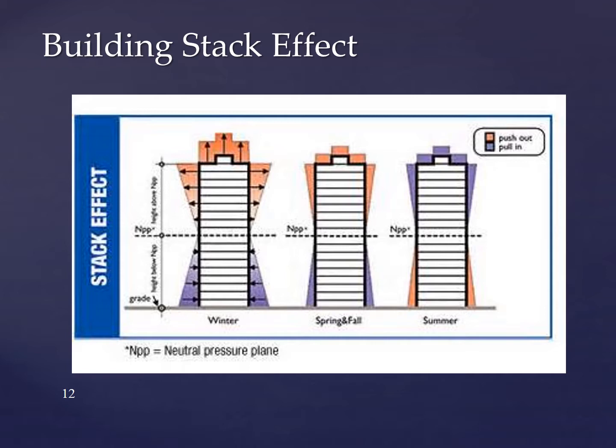Something else that we don't often think about is stack effect. This is a great diagram that shows how air movement changes seasonally. This is one of those things: our buildings breathe. They're living, breathing. Our envelope breathes. Those of you who have elevators or are very familiar with elevator operation, you have air dampers at the top of your elevators, so it can release the pressure as the elevator goes up and down. Very often, those dampers get stuck, or they get rusted, and they don't open or don't close, and they stay open, which creates and accentuates the breathing issue as it relates to the building.